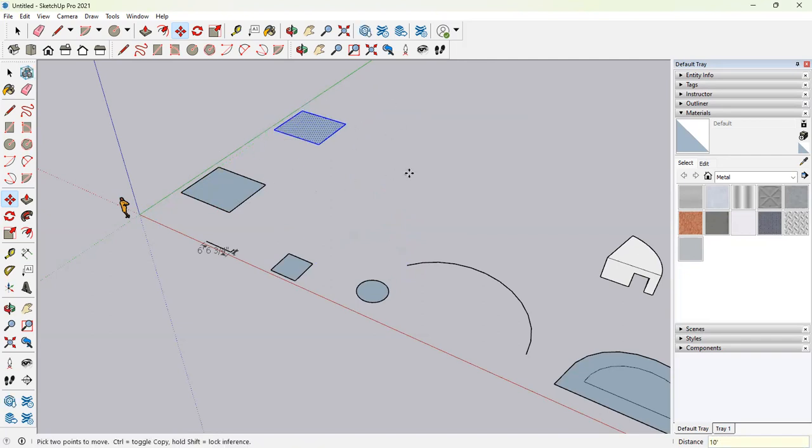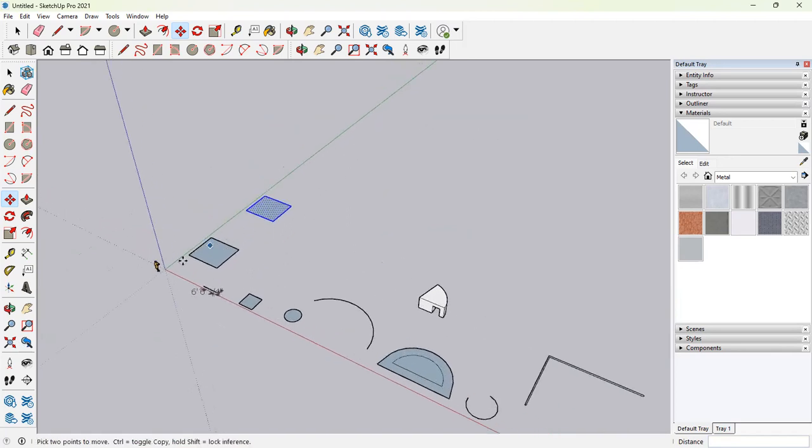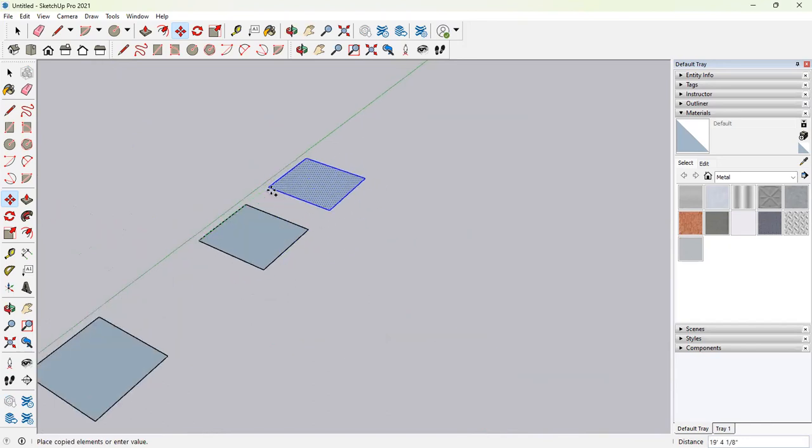It will get copied. If you want to make multiple copies, you will select the object. You will again hit the endpoint. You will hit Control, and now you want to specify the distance. So let's say the distance is 20 feet. I hit enter, it's copied. Now, without pressing anything on your keyboard, not even the mouse, you will type in X, say 10.